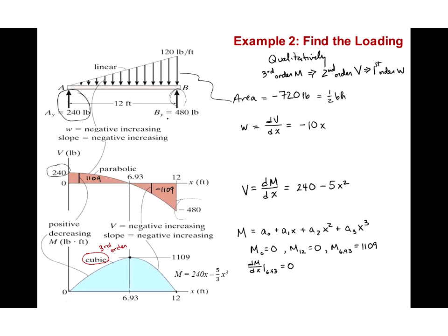Okay, so again, that allows us to see how we can calculate shear and bending moment diagrams and to draw conclusions from looking at shear and bending moment diagrams. Again, the main idea is that you can slice a beam anywhere along its length using a variable x for the position, and use your basic approach of drawing the shear and bending moment at that cut portion and solving for the equation, and then also using these simplifying relationships that the value of the intensity diagram corresponds to the slope of the shear diagram, and the value of the shear diagram corresponds to the slope of the bending moment diagram.